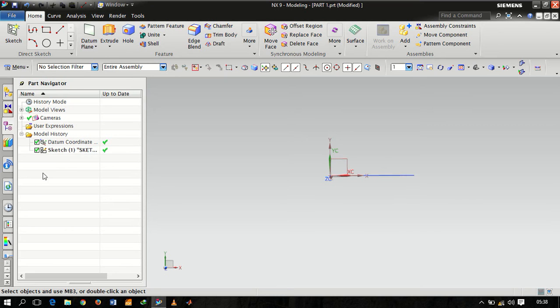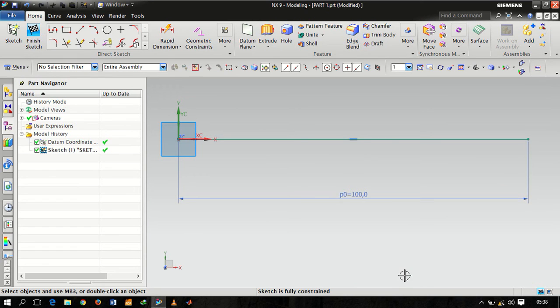Now, in case you made a mistake in drawing the sketch and you want to edit something, how do you do that? Well, you can delete it and create a new sketch by the old procedure, or you can just double click that sketch and you see certain things over here. What you see is 2 points, so 1 and 2. These are the two endpoints of the line.